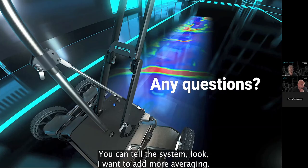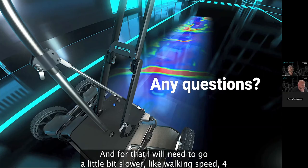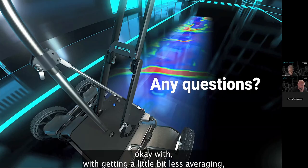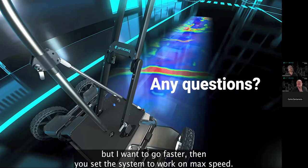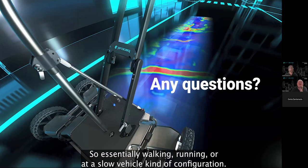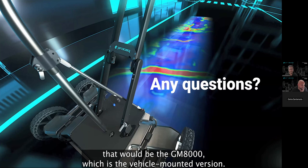You can tell the system, look, I want to add more averaging into the signal. And for that, I will need to go a little bit slower, like walking speed, 4 kilometers per hour or something like that. Or I mounted it on a quad. I'm okay with getting a little bit less averaging, but I want to go faster. Then you set the system to work in max speed. So the system has 3 modes: essentially walking, running, or a slow vehicle kind of configuration. Of course, if you want to go faster, then the product for that would be the GM8000, which is the vehicle mounted version.